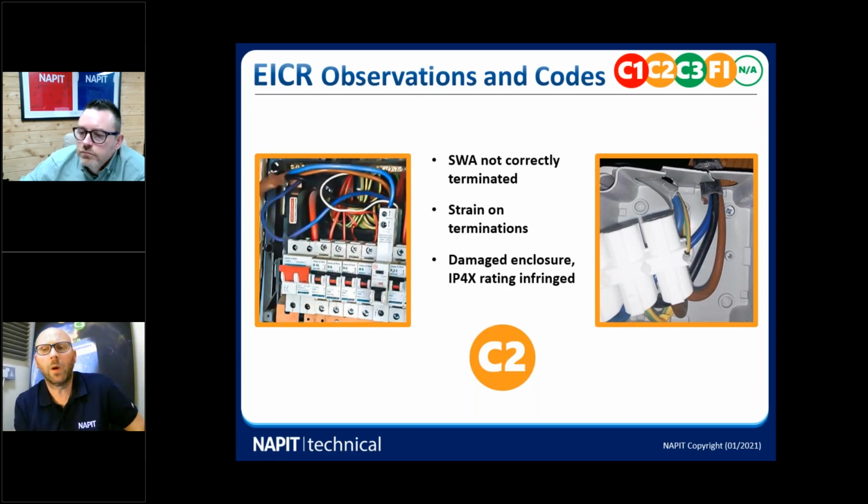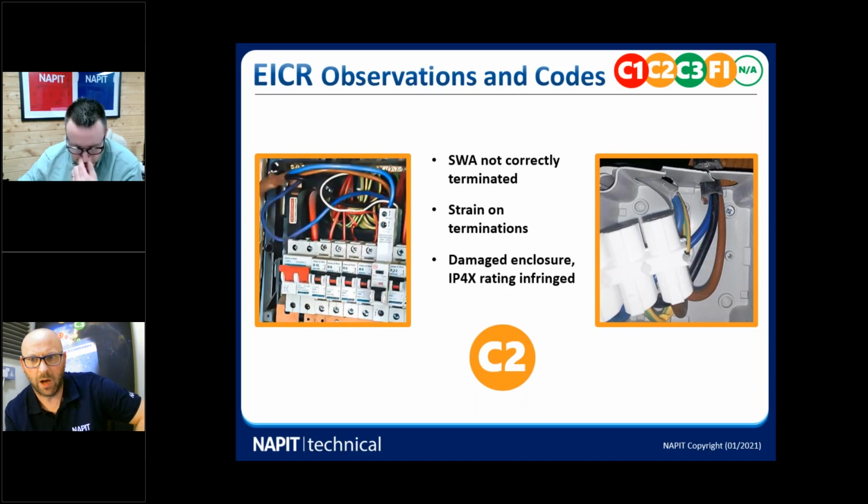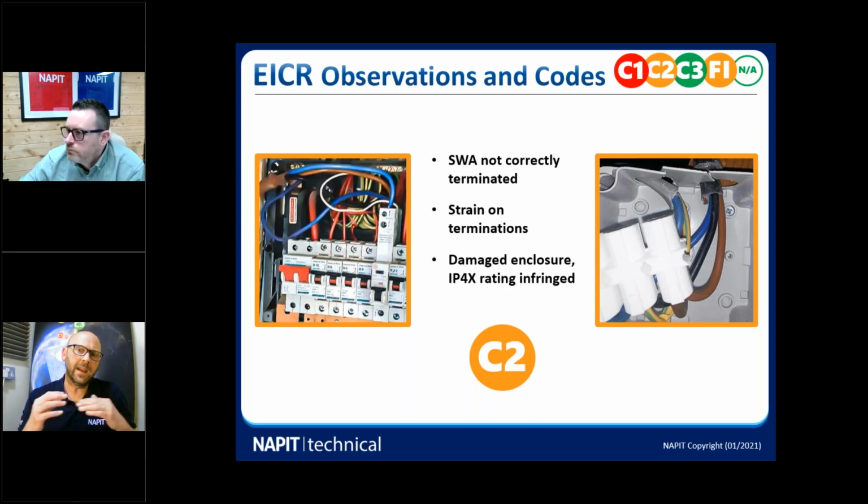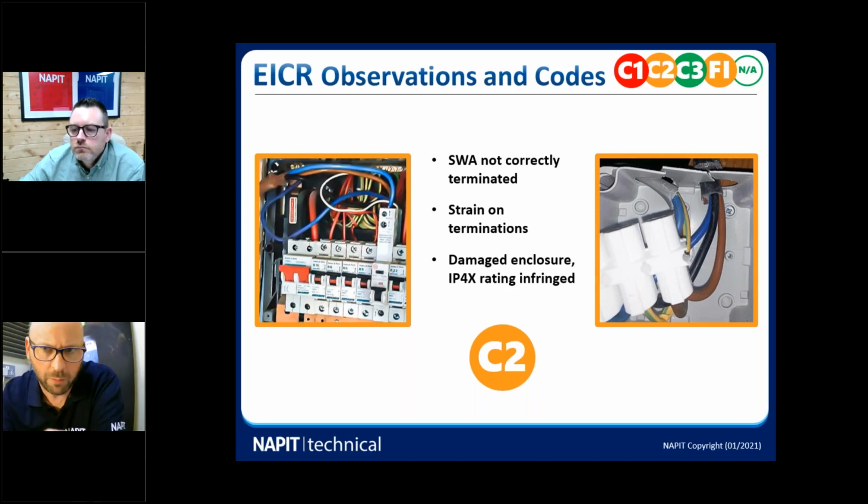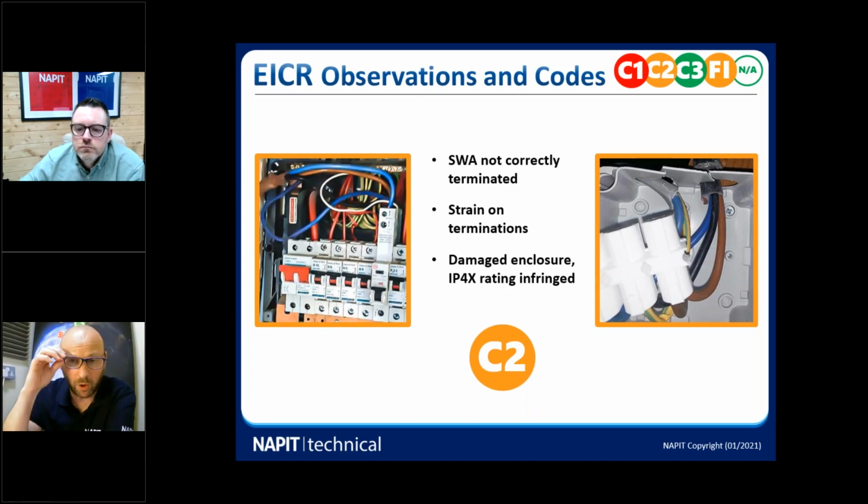We're going to assume that you couldn't push your finger in that box on the right hand side and touch anything live, so we're going to make that assumption with the size of the cables, etc. And assume also that usually when those lids are screwed back in place, it's probably keyed into the box itself, holding it slightly stiffer than what we're looking at there now, but it's got the potential for danger, C2.